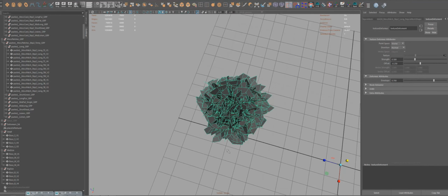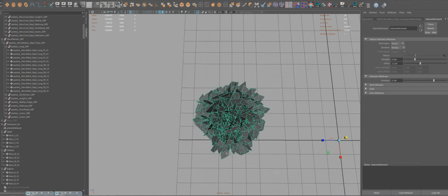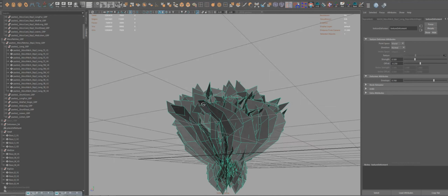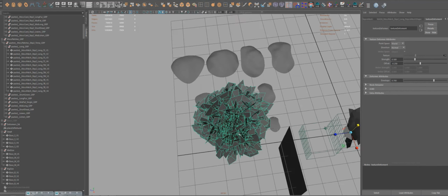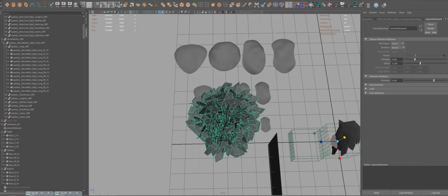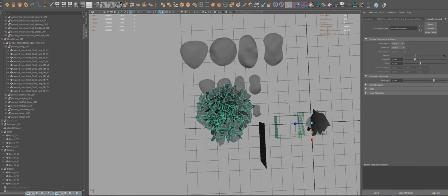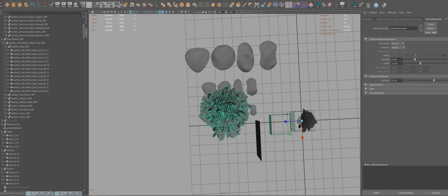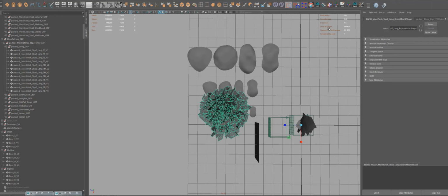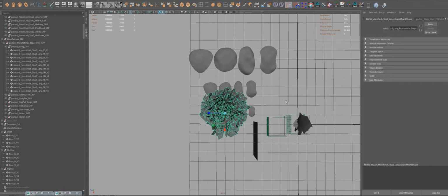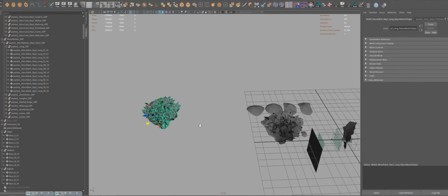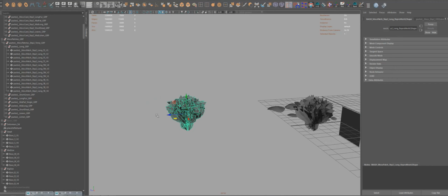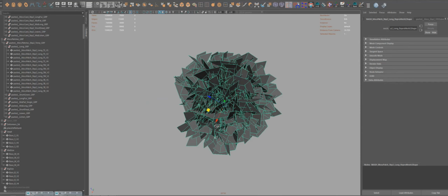So finally, we have all the deformations and all the forms and shape that we need at this point to take this to a final scene, to a render scene. So I'm going to duplicate this patch, center the pivot, and delete the history. Put it to the side, and as you see, we have our first final result.